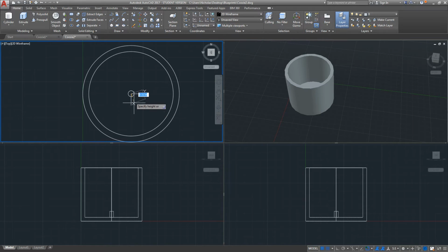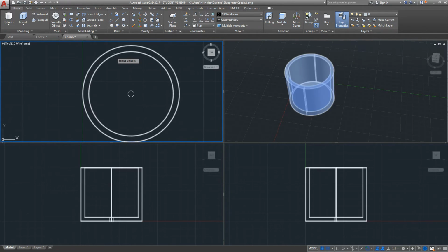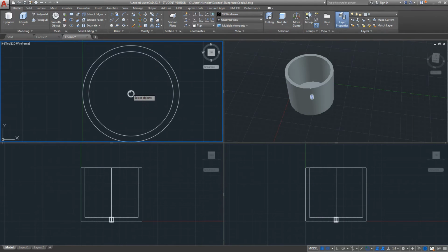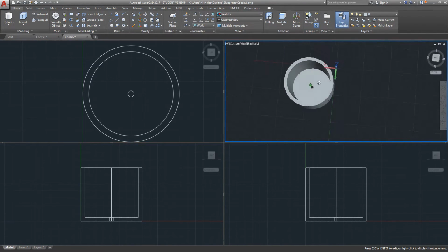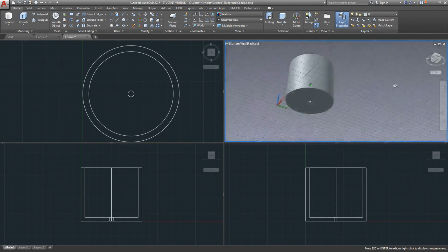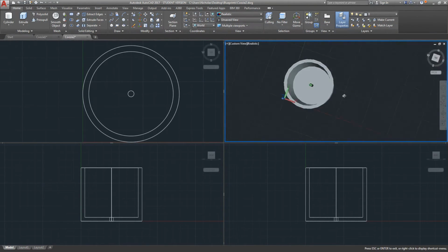So I did 0.125 inches, which is a 1/4 inch of width, and of course as a radius, so you double it because that's the diameter. 2x radius, and then of course I want to go down. See how it's click to the top of that? You go minus. I like to go a little bit more than the thickness. Negative 0.3. Now what do we do again? Subtract. Keep object. Remove object. Boom. Look at that. Check that out.